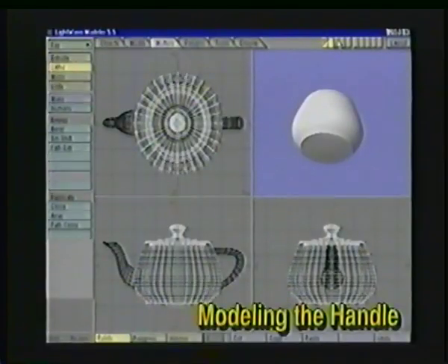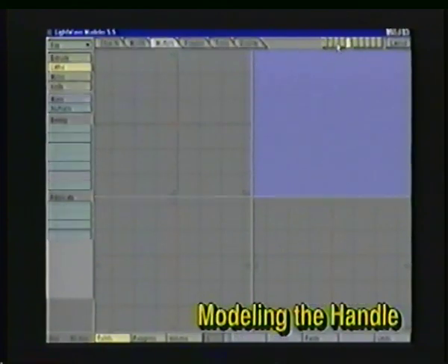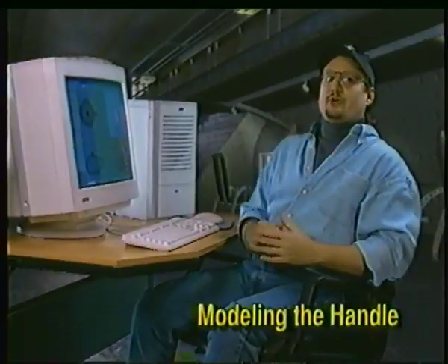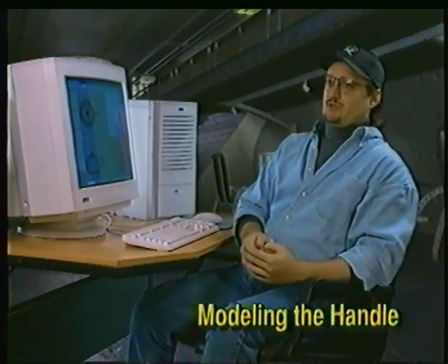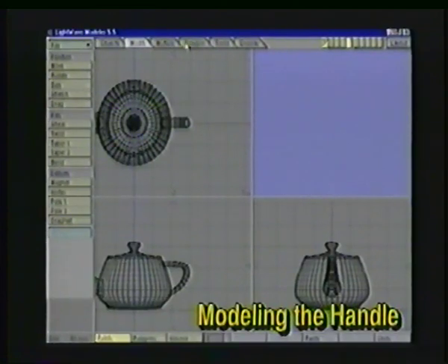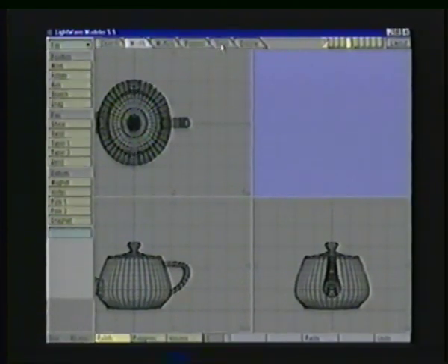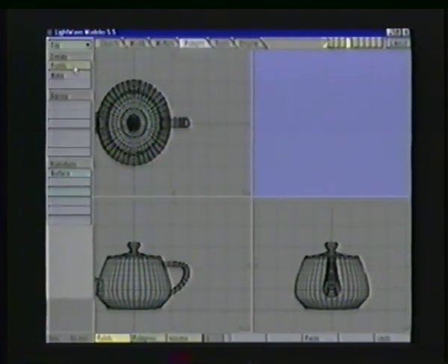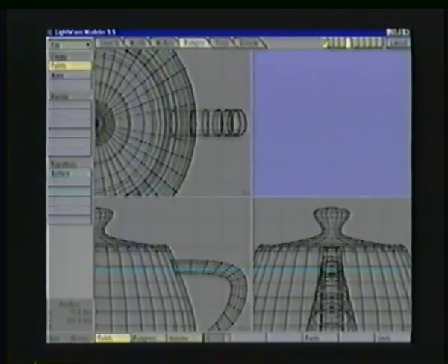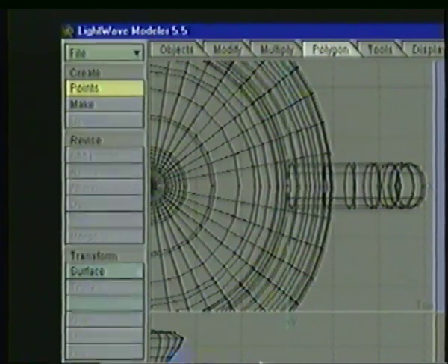This will be quite simple. I'm going to keep the teapot in the background and go to another empty layer. Let's use a spline curve in another fashion. So what we're going to do is, instead of lathing the spline curve, or instead of spline patching, which we'll be doing also in a minute, we're going to use this spline for something called a rail.